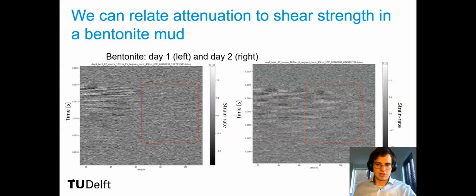This means that the heat from our heating rods has not yet reached our fiber due to a difference in heat conductivity between water and mud. We can also observe a somewhat linear trend in the water when we start heating on the left, and a very different trend on the right in the mud. This is most likely not only related to a difference in heat conductivity, but also related to a difference in heat capacity.